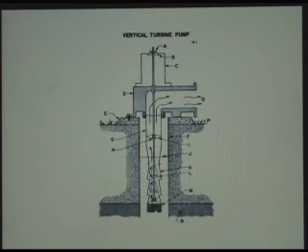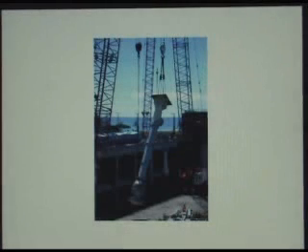So this is what it looks like in operation. Nice big pit, this line. The other thing is it has to be extremely accurately set up so that it sits within the containment shell. If you have it off at any kind of an angle, you end up running into the sidewall. You have to make a lot of adjustments. And they're big. They can be quite big. Since NPSH was the problem before, they just make the pump as deep as it needs to be to satisfy the NPSH requirements for the impellers inside the pump, and that's usually between 18 and 25 feet, sometimes longer.